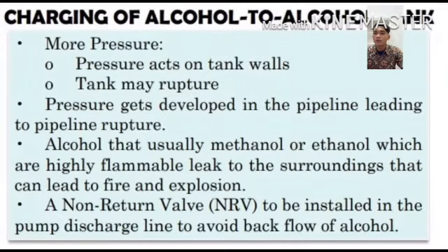For the charging of alcohol to the alcohol tank, more pressure, which is pressure on the tank wall, means the tank may rupture. Pressure gets developed in the pipeline leading to pipeline rupture. Alcohol, usually methanol or ethanol, is highly flammable and can lead to fire and explosion in the surroundings. A non-return valve NRV should be installed in the pump discharge line to avoid back flow of alcohol.